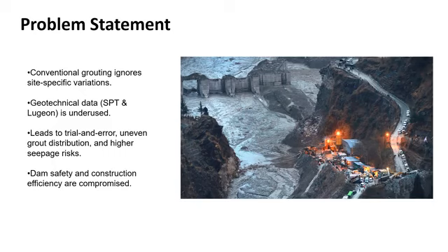In Sri Lanka and many other places, dams often face seepage issues due to natural variability in geology and rock fracturing. If untreated, seepage can cause increased uplift pressure beneath the dam, leading to instability and even potential failure. A grout curtain acts like an impermeable barrier beneath the dam, reducing water loss and lowering uplift forces. However, the curtain must be carefully designed to prevent excessive hydraulic gradient that could cause erosion along partially sealed fractures.